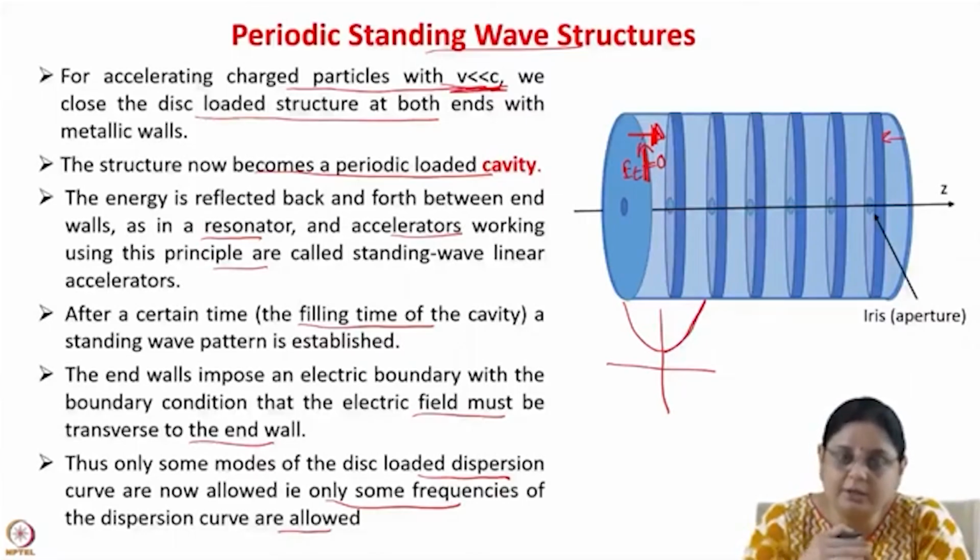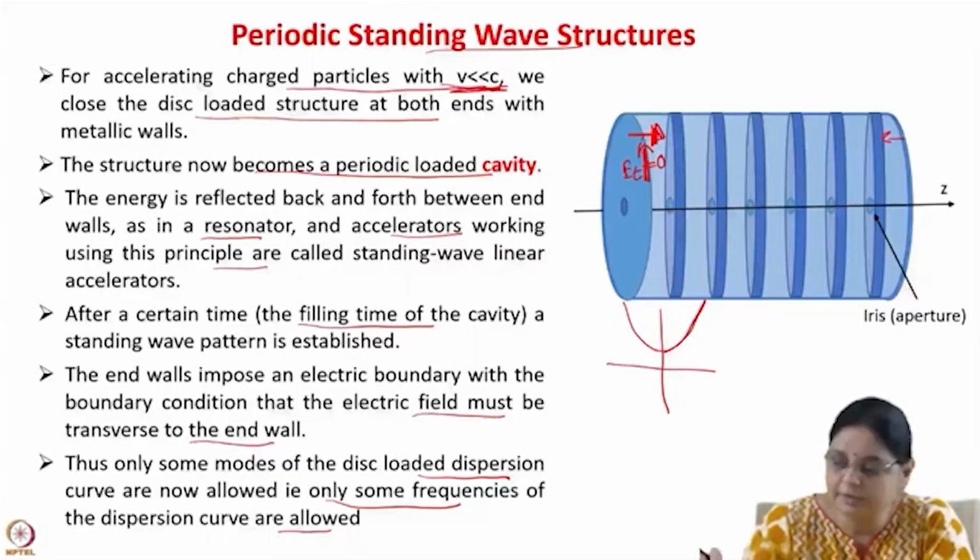In a waveguide, because it is a propagating wave, any frequency above the cutoff frequency will be propagated. Whereas in a cavity, only at the discrete frequencies does the power go into the cavity and form the mode. Electromagnetic waves at any other frequency will be reflected back.